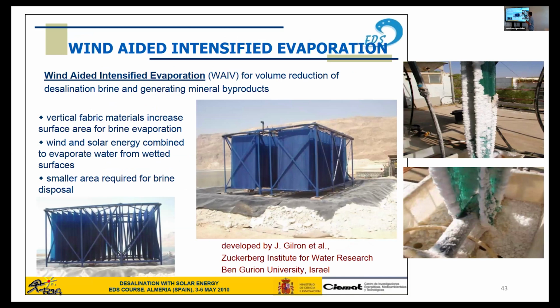There are also interesting systems that I have explored, enhanced evaporation and enhanced extraction of these salts. A very interesting example is the wind-aided intensified evaporation, the so-called wave systems. Basically, they have a percolation wall where they flow the brine in various thin films to a wall, and via the action of the wind, you have enhanced evaporation and crystallization, which can be more easily recovered. You can then have a large production of salts for the total amount of area, in a much more compact system than what you would get, for example, in ponds.